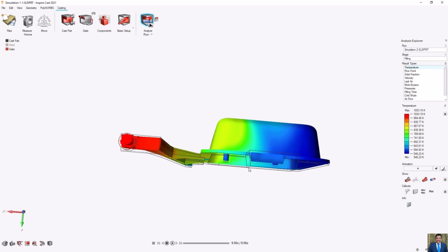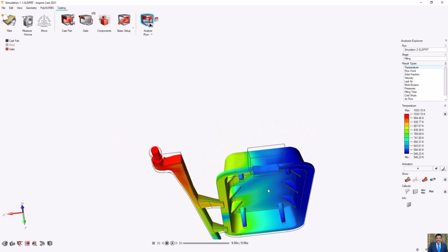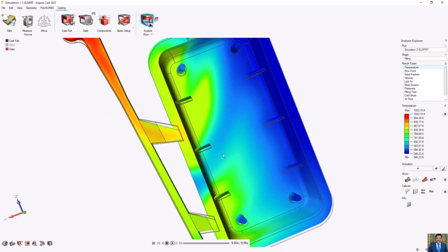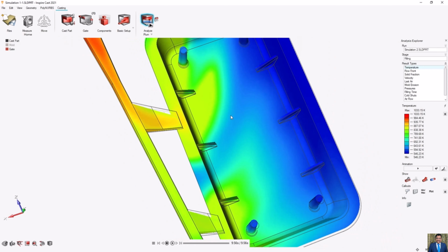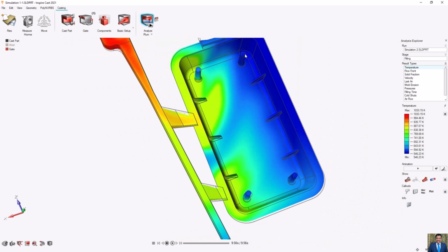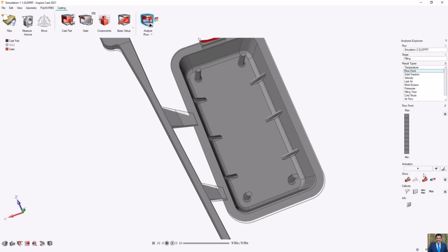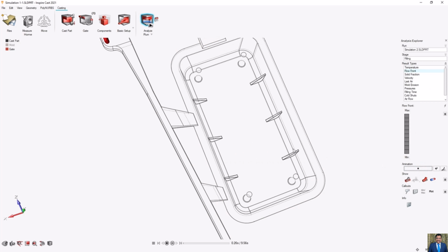But when we make a design for the mold, we need to think about the rib here. We need to think about all the ribs. And also we need to think, because air is stuck here in 4, and also in the rib air is stuck, and we need to think about it. You can see a little better for the air when it's stuck.